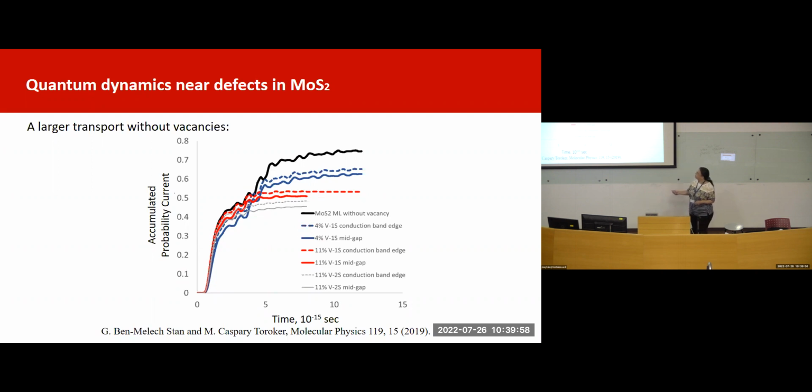You can see the mid-gap state is not so trapping at all. It actually is a large contribution. The dashed line is quite high. And we did different analysis techniques, using what we will not discuss today, non-equilibrium quantum mechanics, to see that that state is not really bound. It's part of a continuum and it contributes to current.